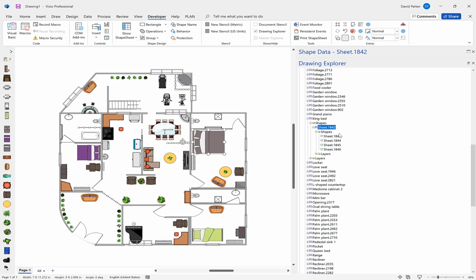Now what I can see immediately is that these four shapes inside there have not got any layer assignment to them. So even if we're switching off, and we can see the top layer is assigned to furniture and movable furnishings, it's still not going to switch off the graphics, which is bad, really. That whole thing should have been corrected.